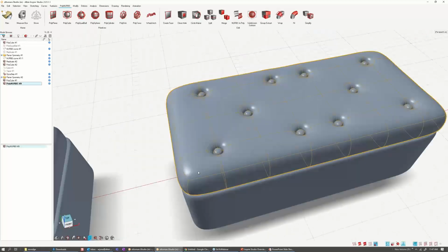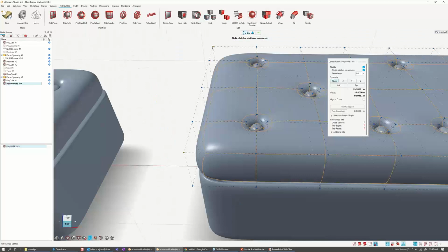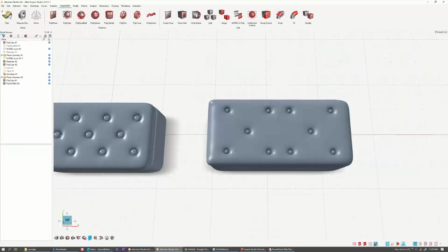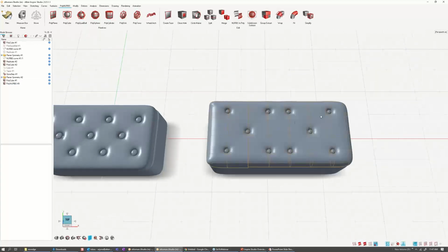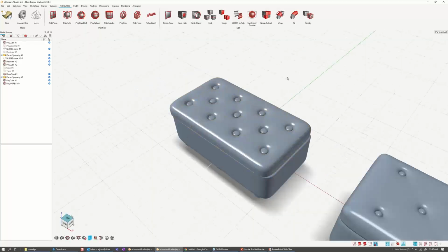You can also do some more additional details using the same chamfer technique. If you select the end points and do a chamfer, it's going to give a different look here too. So a lot of things can be changed. You can also add some more chamfers along the edges if you want. So yeah, that is a quick way to create some objects like these.